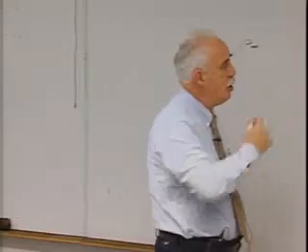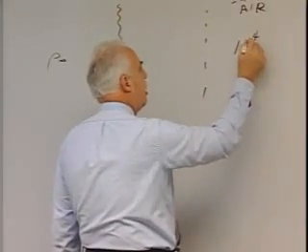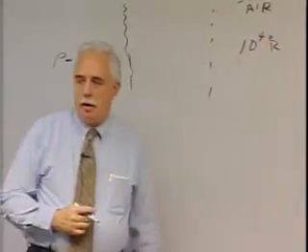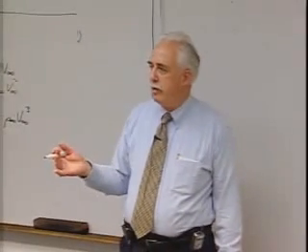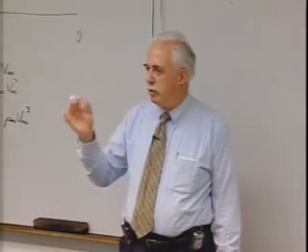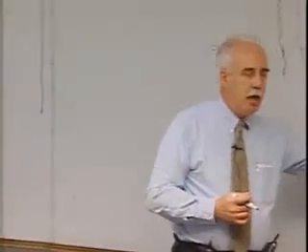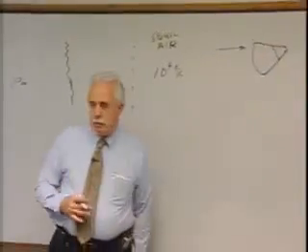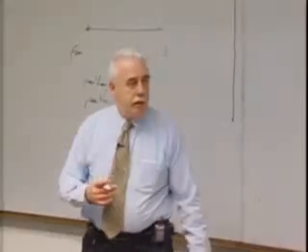Here, once you get to equilibrium, you're operating at a temperature of about 10 to the 4th degrees Rankine. The effective black body radiation from the sun is 10,000 degrees Rankine, the distribution in terms of the spectrum. That's the temperature of the gas at equilibrium. At the wall of the vehicle, perhaps 6,000 degrees Rankine, and we'll get into that a little bit.